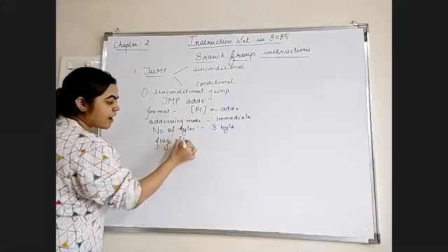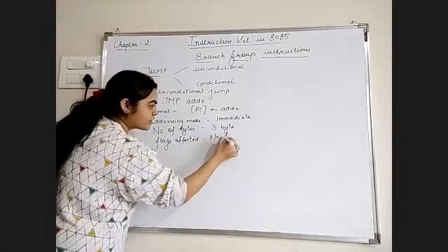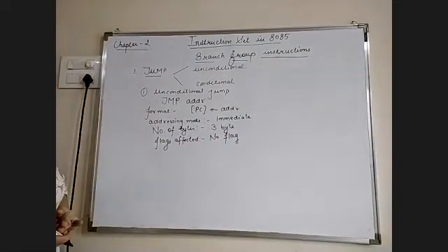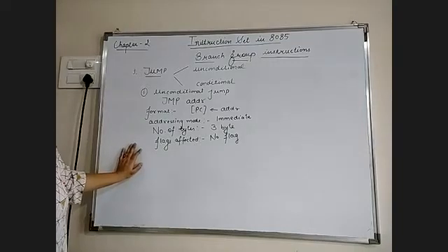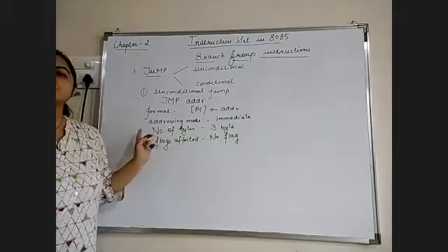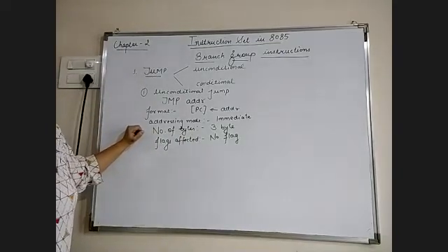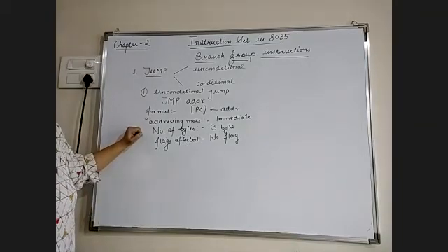So by any of the branch instructions, no flag will be affected. Why will no flag be affected? Because these branching instructions only change the sequence of the microprocessor from one memory location to another. That means only the program counter contents are changed from one memory location to another. So for these branch group instructions, the ALU is not used.